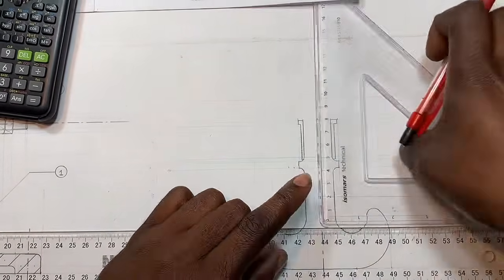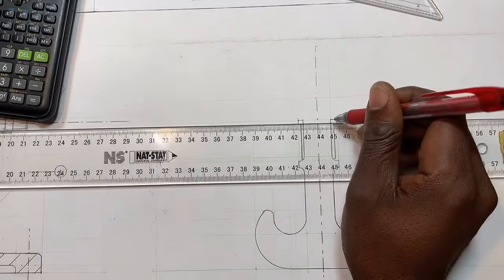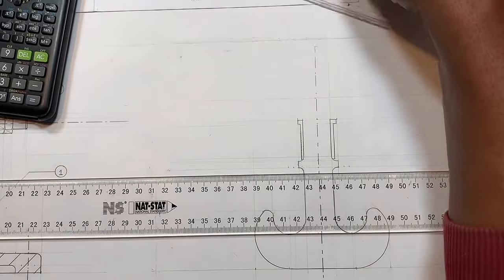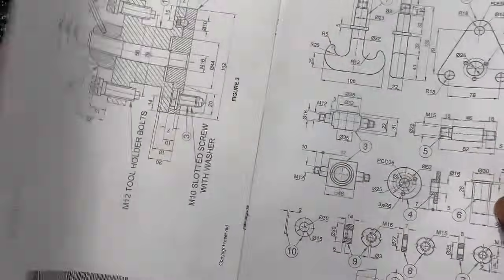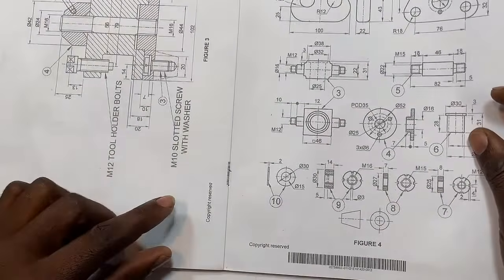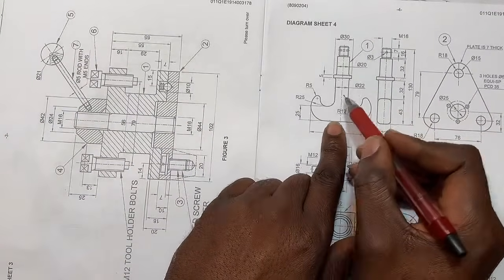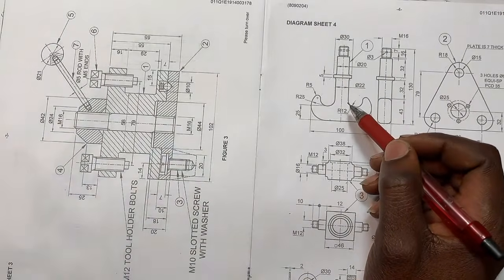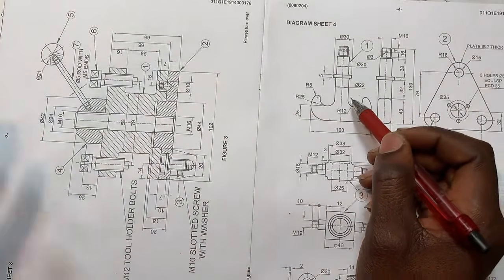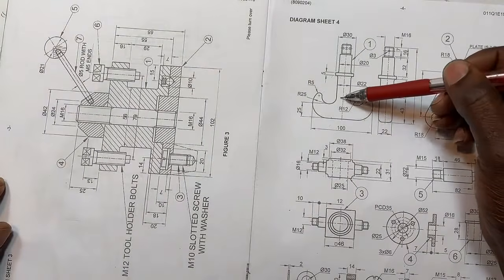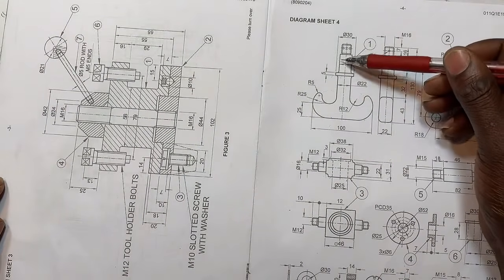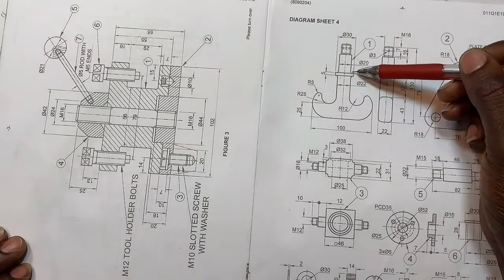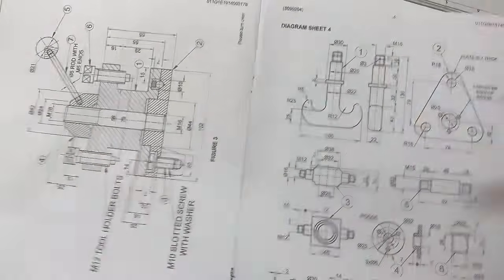Okay. So we're not quite sure whether this one is going to close here. When we take a closer look at the shaft of ours, we do not have a section when it's cut along its length, I mean, along its height. We don't section, because from here till here, going up, is in the shape of a shaft. So this one, we can leave it solid.